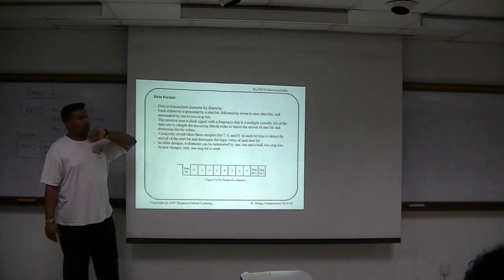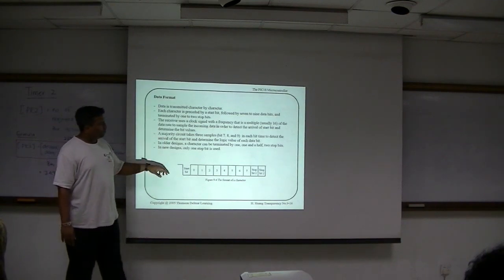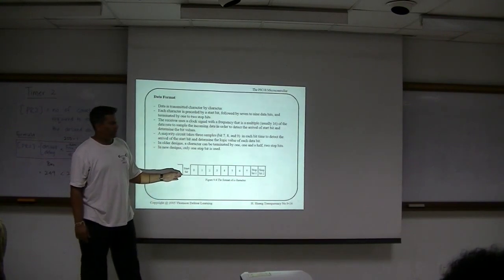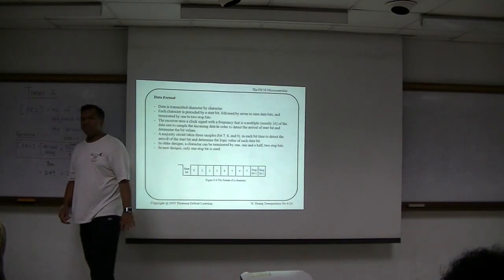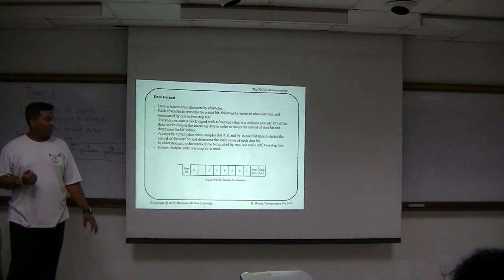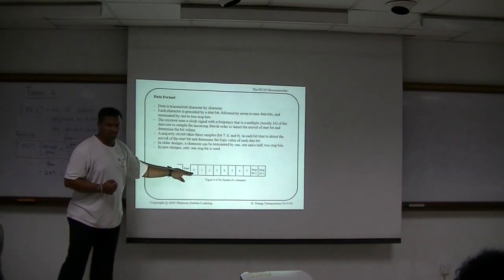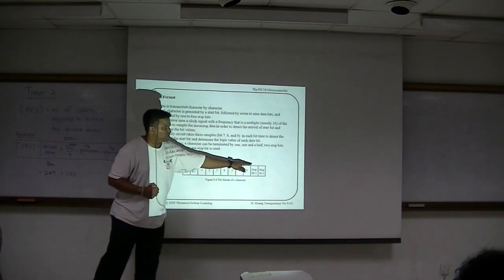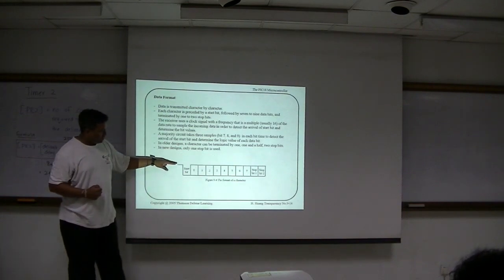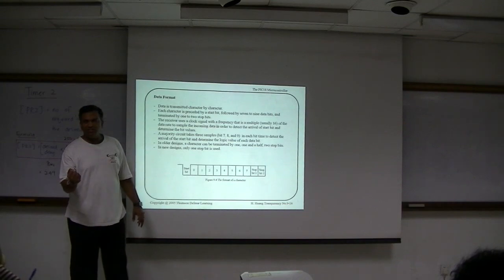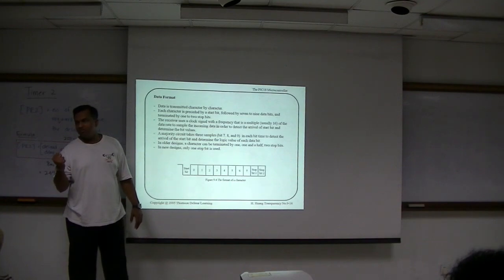And it is terminated by 1 or 2 stop bits. So always remember, the data will be preceded by a start bit, and you have a stop bit. Now why do we need this start and stop bit? This is so that the receiving side will know. The start bit always gives logic 0, and the stop bit is always logic 1. So after logic 1, the start bit will give logic 0. The first logic 0 that it receives, it acknowledges as, okay, now start.